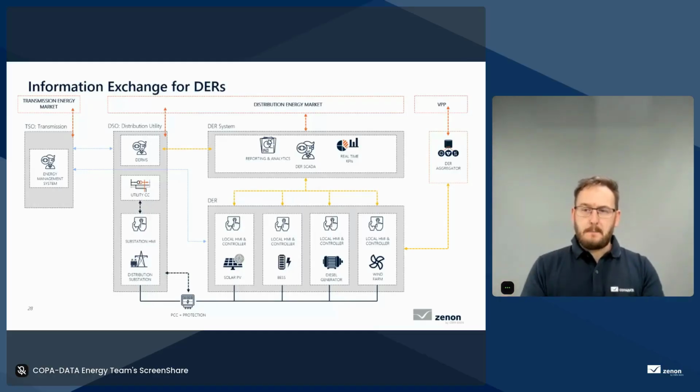On the right would also be a use case for a DER aggregator, which could provide data about the DER to a virtual power plant, for example. So a virtual power plant, regardless of where the DERs are geographically located, thanks to the DER aggregator, can consolidate multiple DERs in one system and then react based off of market needs and also the situation or the status of each of the DERs.